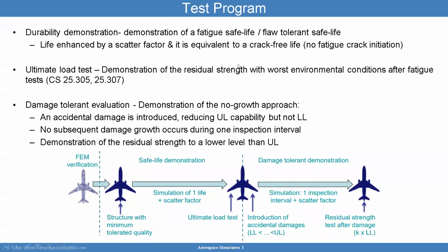So what does the test program look like? You have the durability demonstration, which is the demonstration of a fatigue safe life, flaw tolerant safe life design. And usually the life is enhanced by a scatter factor and it is equivalent to crack free life. So no fatigue crack initiation.